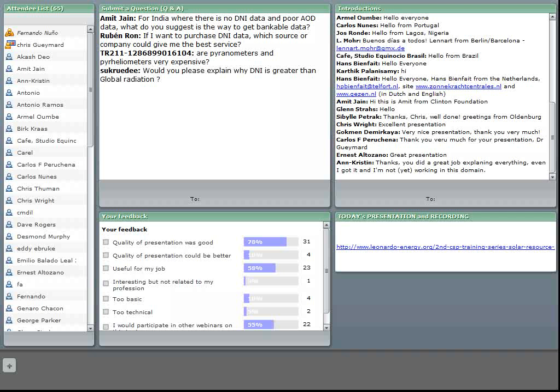So in some cases, especially in early AM or late PM, DNI will be a lot more than global horizontal. Global horizontal is affected by the cosine of the zenith angle, whereas DNI is not. And that's why DNI can be more than global.